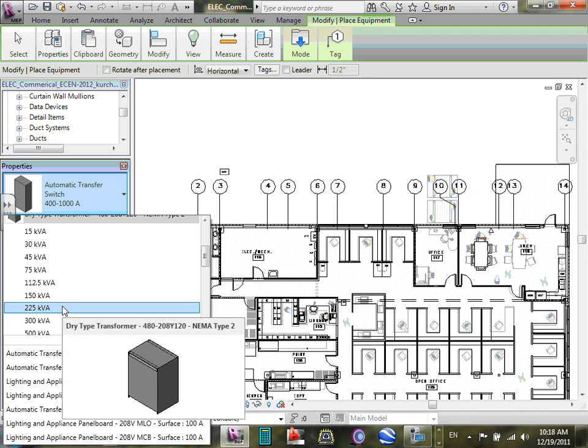Why 125 kVA? Because I did my math for a 500 amp panel. I need 180. Well, we usually don't size this. We're going to go to the next standard. We're going to assume, really assume here. We have no control over this. The Excel is giving you the next standard up, which is 225 kVA. Is this the right transformer, Ashley? Where did the info about it come from? Is this the right transformer?